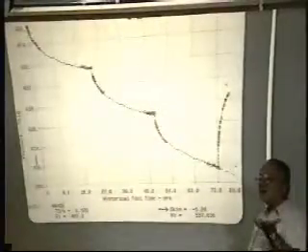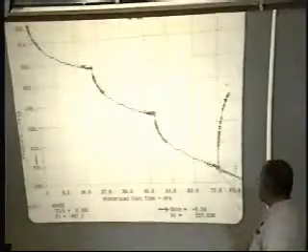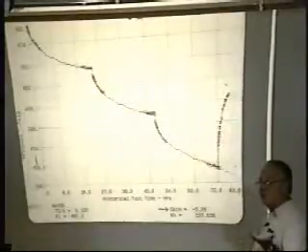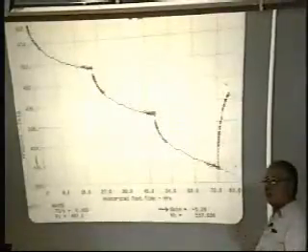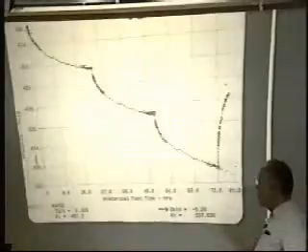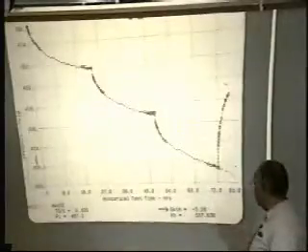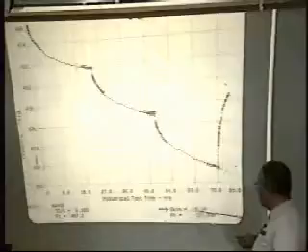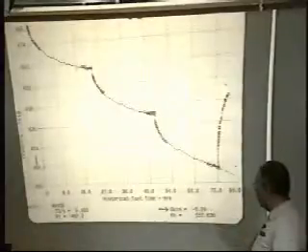And the last flow rate was a reduction in flow rate. So this looks like a buildup, but it isn't. Because you cut the flow rate back, you had an increase in pressure. So all these transients have been accounted for in a solution. And here we get a skin of about minus 5.3.